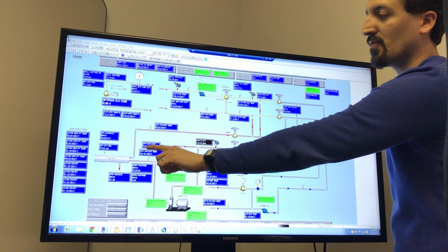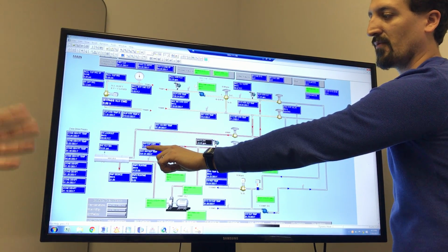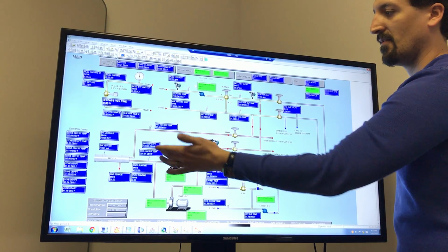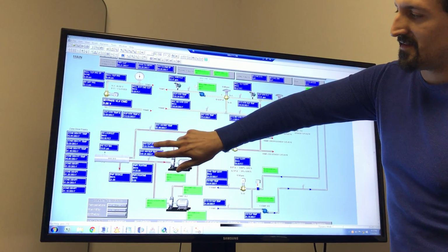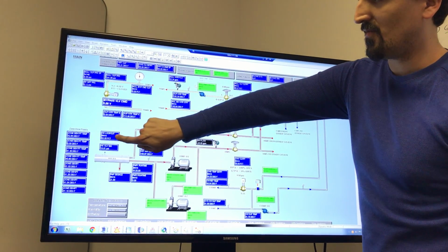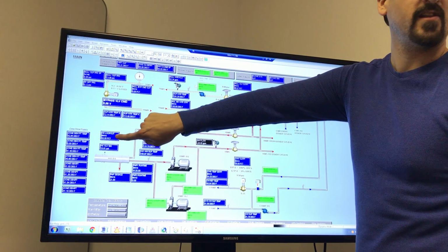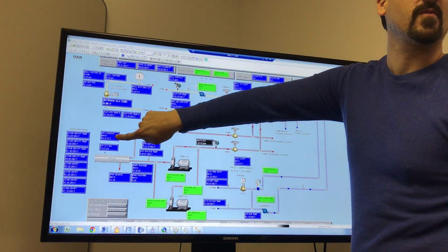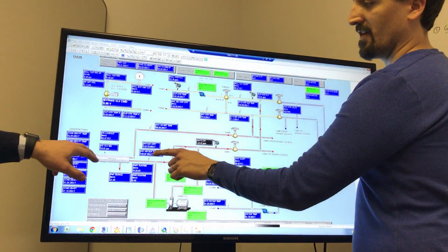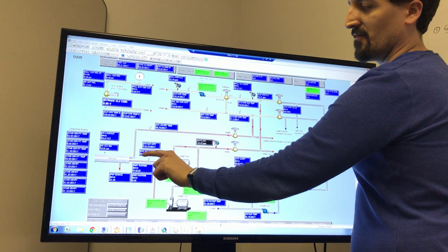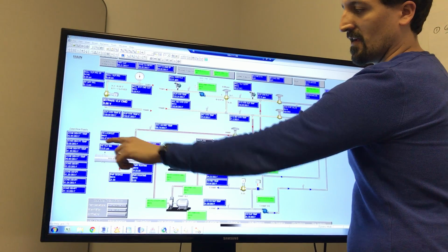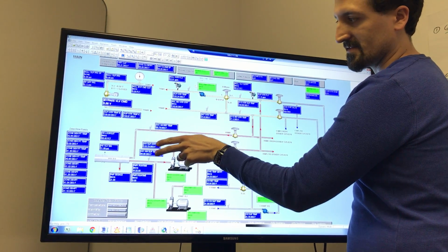Outdoor temperature. So the colder it is, the higher the hot water supply set point, up to 140 probably. They have limits, so based on outdoor temperature you would never get 140 today. The delta between this and this controls the third PID loop, which turns on the heat exchanger control. This is the source from the plant, and I'm much lower, so this one increased. And you will see if you keep controlling, this will increase to try to close this error.